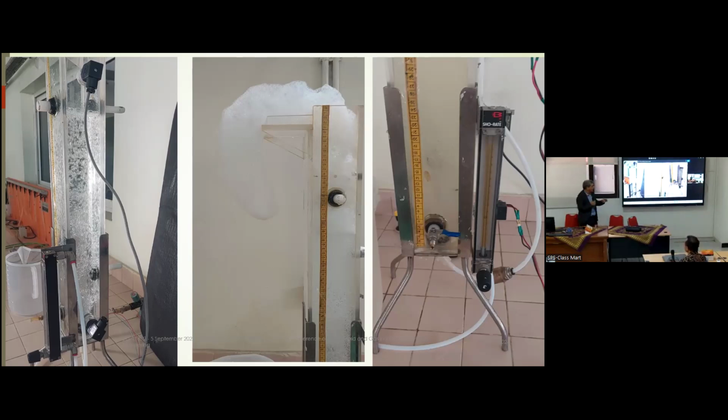For example, the air bubble contains oxygen. And the oxygen quits the bubble to the liquid, and there is a reaction after mass transfer. The size of the bubble is very important, because if you have a large bubble, the large bubble has a high velocity and quits rapidly. That's why we choose the fine bubble, because the fine bubble rises slowly, and we have time to have reaction or flotation or something. Okay?